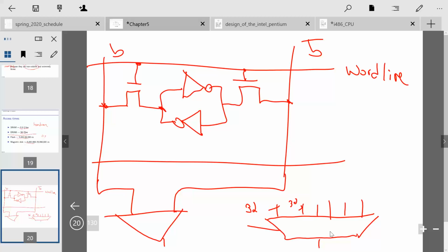So that's how data moves through the SRAM, and that's why larger memories are slower: they have larger row and column decoders, which have an increased propagation delay. They have longer word lines and bit lines, and the sense amps have to be bigger, and all of that. And then just real quickly,